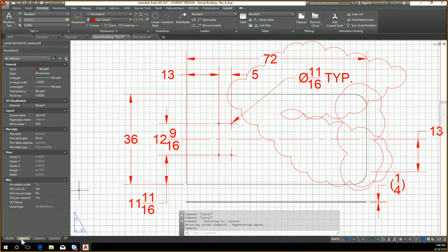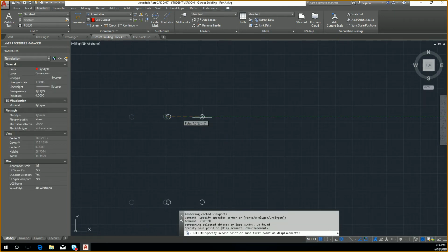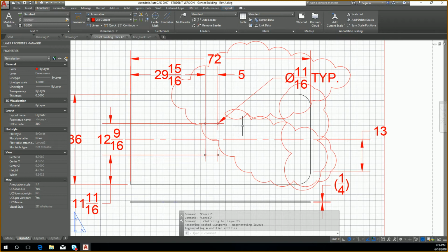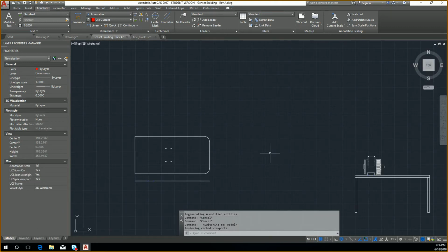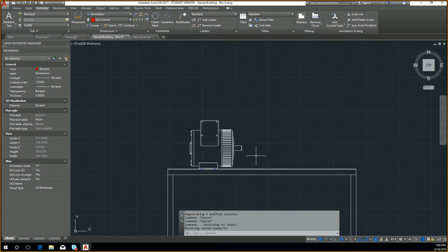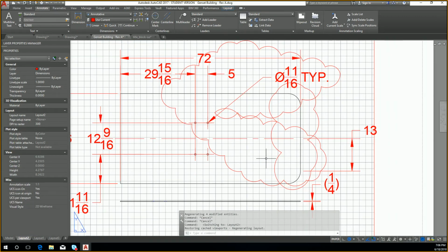So if I had shifted this over, just like my revision comment said there, somewhere over there, and it's almost twice the distance over now, it looks fine, right? My motor's still gonna fit. But if you remember back to what we had learned, this motor had the drive shaft pointed in towards the table. So typically that motor will be driving something else. So what if I typically needed the full remainder of this table to support whatever I was driving? That one little change that you thought was fine to do might have the effect of you no longer having room to support your following assemblies.